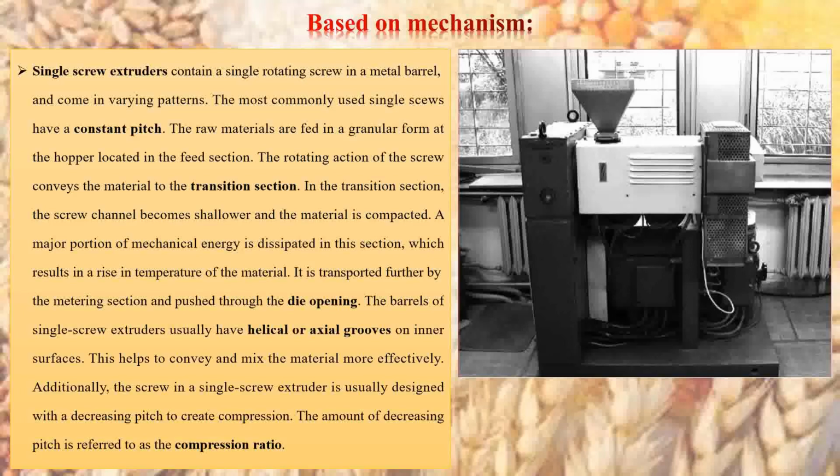A major drawback in the single screw extruder is that the processing is almost incomplete and it is very fast, but not a radical approach in the sense of proper mixing. So often the set of mixed ingredients is recycled within the extrusion chamber, and so the cost of unit operation is a little bit higher, or I must say it is higher, when we are going to have a particular product, a pellet size product, or